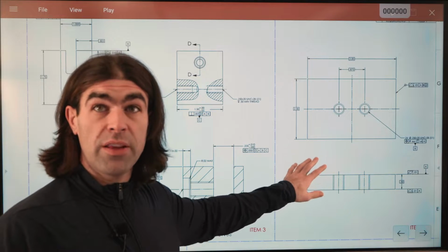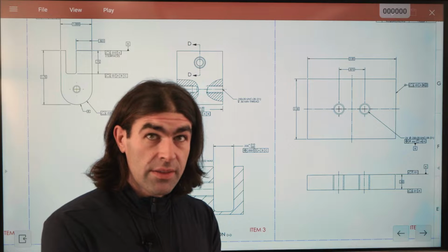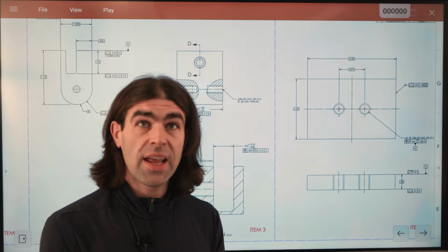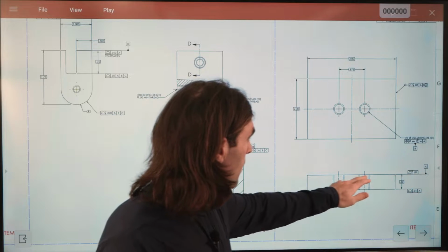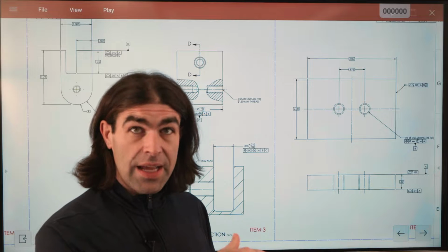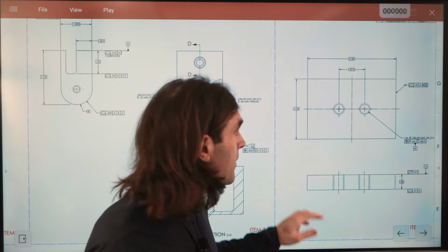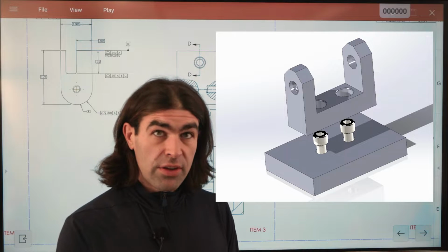This is our base plate. The way I've dimensioned this, because all it does is hold the thing steady on a table or whatnot, we've got datum A, which is this flat plane. It's going to mate to the next piece, so datum to datum contact. The two threaded holes that the socket head cap screws go through are considered a datum.